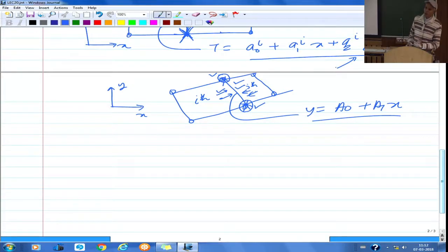So, you have the bending part of the strain energy and the transverse shear strain energy. Rather than doing the exact integration of the stiffness contribution from the transverse shear strain energy, you do the integration with 1 point numerical integration. So, that is what is known as reduced integration. So, that was another question.